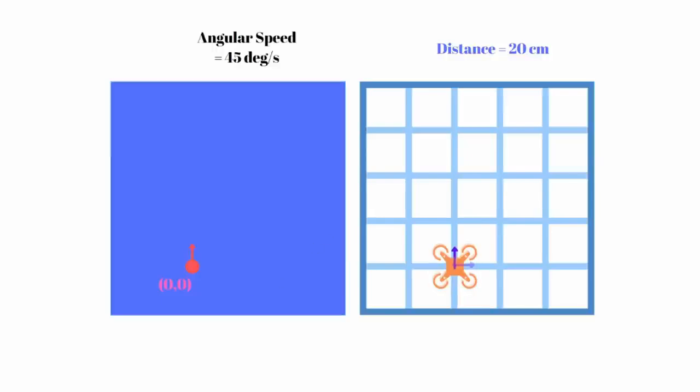north. So what can we do to actually find the coordinates when we are pressing both the forward button and the right or maybe the left button? So we are rotating and we are also moving forward or moving backwards. How can we calculate that? By the way, the angular speed is calculated pretty much the same way that you would calculate the distance. So if you are moving, let's say for 2 seconds, 45 degrees per second for 2 seconds will give you an angle of 90 degrees. That will be your heading after 2 seconds.